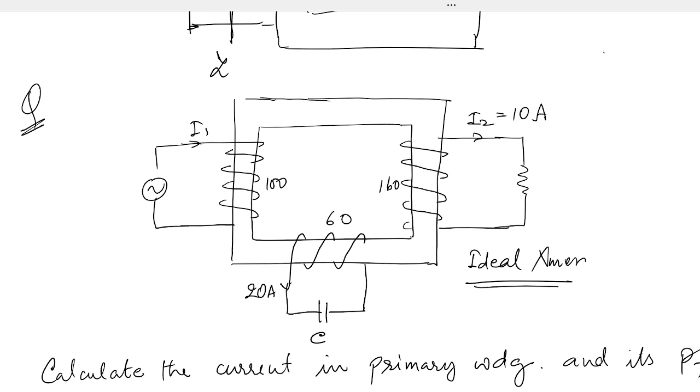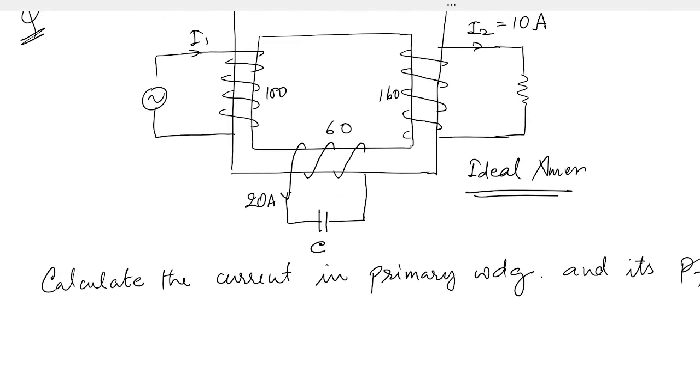I am asking this question so that you have some clarity on how to deal with complex loads. Are you all clear with phasors? For a resistive load, the current will be in phase with the voltage. For a capacitive load, the current will be leading by 90 degrees.